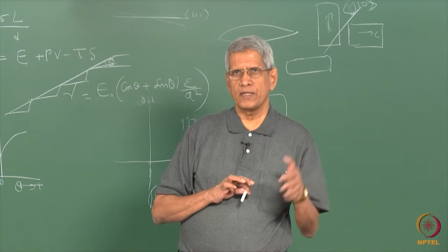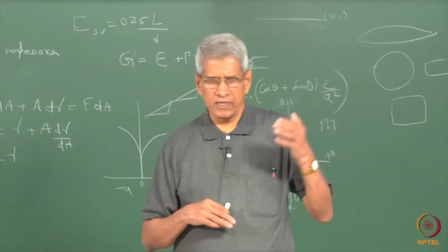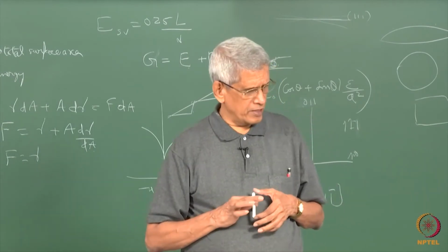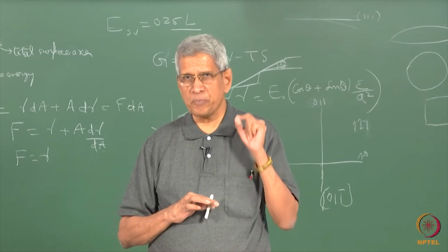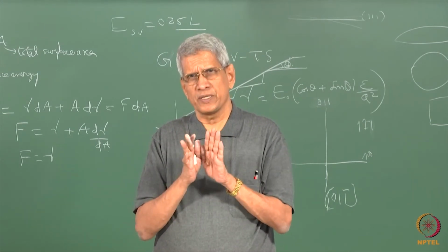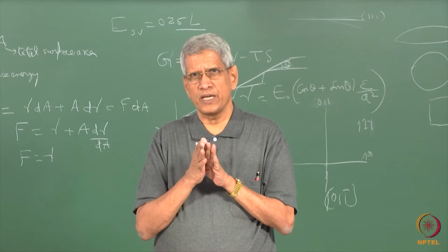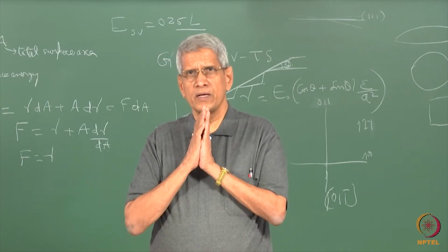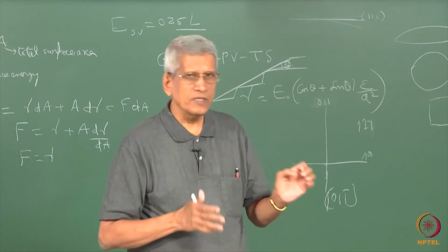Even on these low angle boundaries, depending upon the type of misorientation, the classification we use is tilt boundaries or twist boundaries. Similarly, on the high angle boundaries, some of these could be considered a type of special boundaries. What are special boundaries? Even at high angle misorientation, when the boundary meets, it should be a particular type of interface, like a low index plane between them. Then there can be a cusp in the minimum energy. These are called special boundaries.